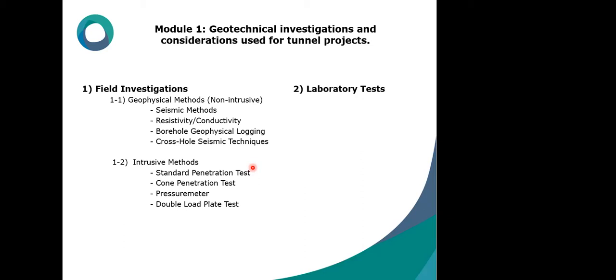Here, we will concentrate more on field investigation because although these methods are more expensive, they usually result in more economical and optimized design. In situ techniques, in spite of their high costs, could be cost-effective for projects in general. We will learn intrusive and non-intrusive in situ methods, and the parameters and information that can be attained by them. Geophysical ways are very beneficial in long tunnels, where we don't have access to the whole length of the tunnel at the beginning of the project.